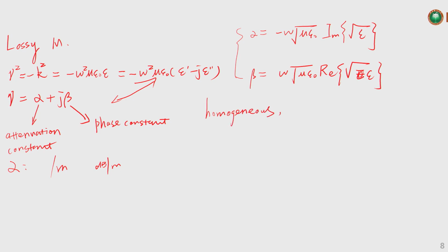First, the material is homogeneous, and it is also isotropic material. So that means if this material is inhomogeneous, for example, if you want to set snow or rain as the medium, and then the EM wave propagates inside of it, because it is not homogeneous, we cannot use both expressions to define the attenuation or the phase variation.